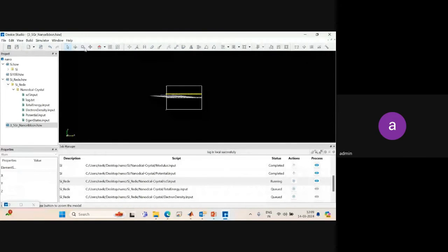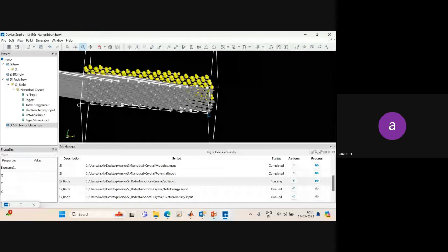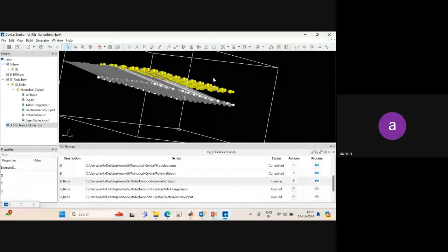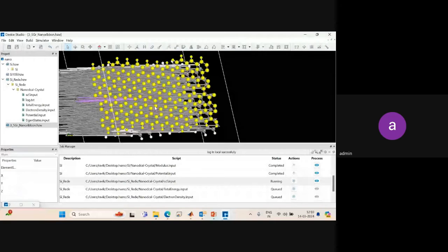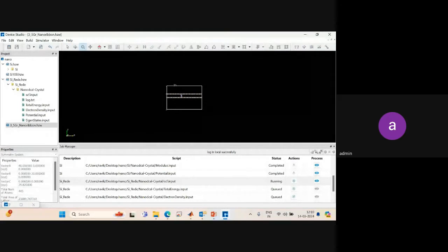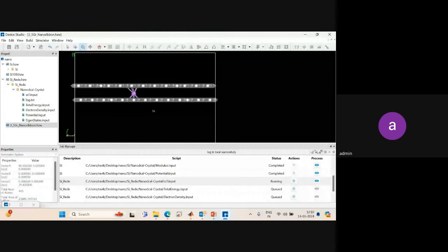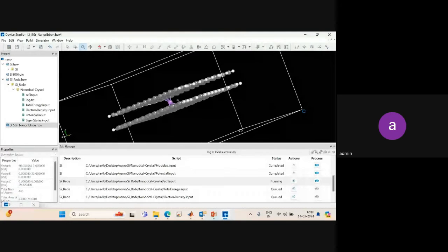Now I can zoom in on this particular unit cell that you can see here. The bonding between all these atoms has been disbalanced. So for that purpose, I will select all and click on recalculate linker bond. Once it is done, now you can see all the bonding is proper and it's ready, with the lithium ion in between.